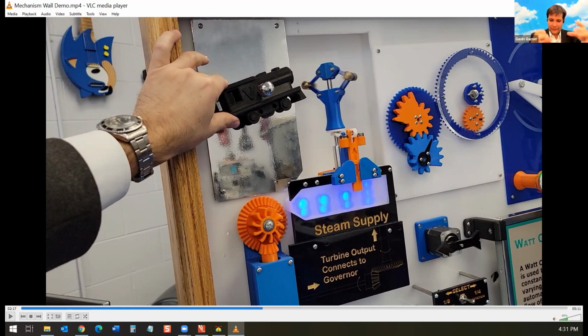So I had basically the same model as this real life tuning fork I had in my hands, ran the finite element analysis, and poof, the fundamental frequency that came back was exactly what was stamped on it. So to me, that's powerful when you get that close with an approximation. Of course, aluminum is isotropic, and that's very easy to model.